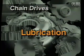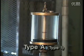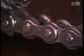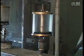Proper lubrication is essential for a chain drive to achieve its potential designed life. There are 3 methods of lubrication. The first is Type A or Type 1 lubrication, involving manual or drip lube. This method is most common when the chain is accessible to maintenance personnel, and is most often done by brushing on lubrication, often enough to keep the joints from running dry. This method limits cost, but it is often the least desirable way to lubricate.